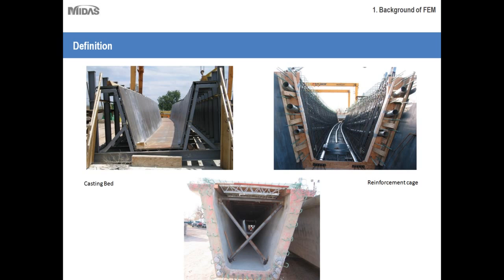The most popular type of construction methodology that resembles what I'm talking about here is balanced cantilever construction, where the segments are shorter in length and they are along a curvature, and then the engineers erect one segment after another. But this section has somewhat revolutionized how the splice girders could be modeled.